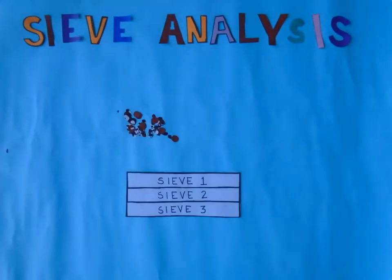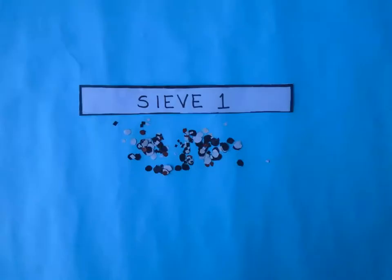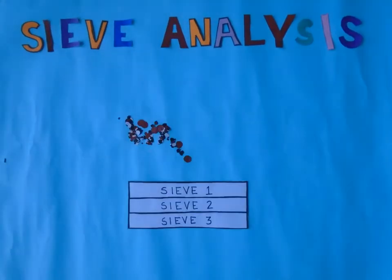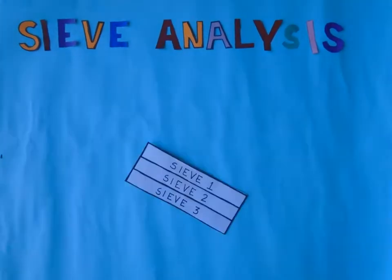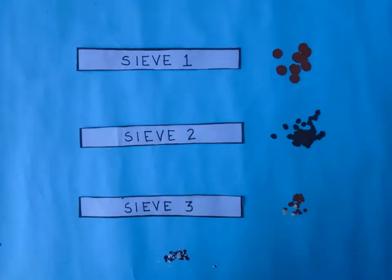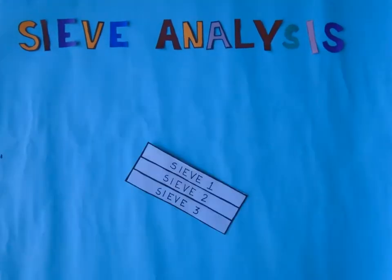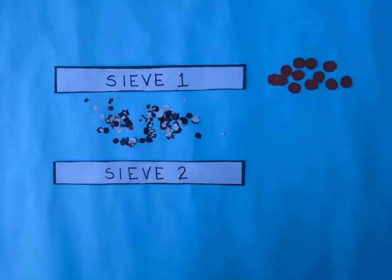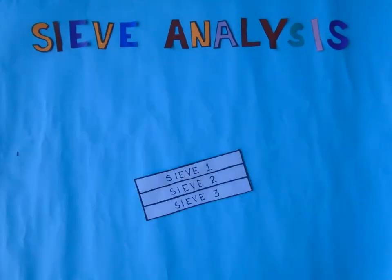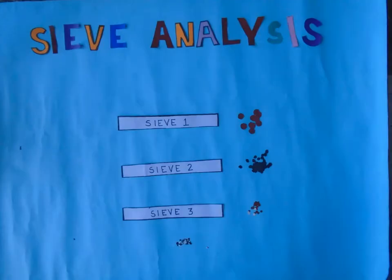Under geotechnical engineering, sieve analysis or gradation test is a very good control and quality acceptance tool for the composition of construction materials. It determines the distribution of aggregate particles by size given a sample. Sieve analysis is used to determine if the aggregate complies with design and production control requirements, verify specifications, and establish relationships between aggregate and aggregate blends. Multinomial distribution can be used to represent the particle size distribution of a certain aggregate sample.